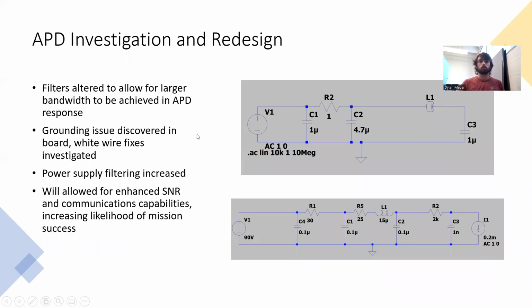So what occurred was filters were altered to allow for larger bandwidth for increased communication abilities. Grounding issues were discovered in the board, and white wire fixes were investigated. We managed to improve the performance via those fixes, and we'll integrate that into the board.